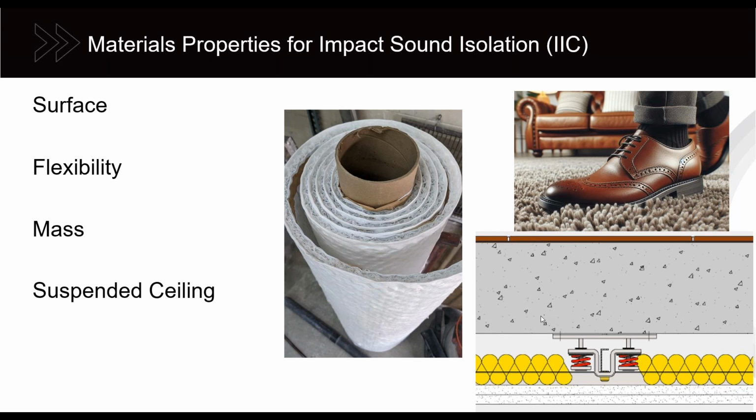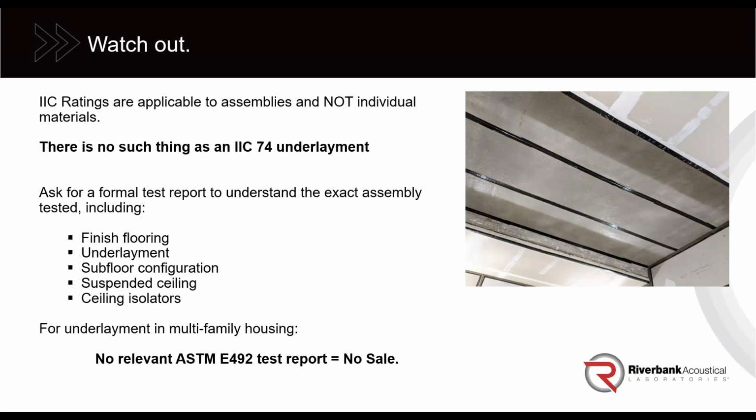That's another trend, as the demand for higher ceilings in condominiums is counter to the interest of the acoustics. So exposed slab configurations, where you look up from the room below and you see the actual concrete subfloor without anything suspended, are important to take into consideration for acoustic performance, because the ceiling can help you quite a bit.